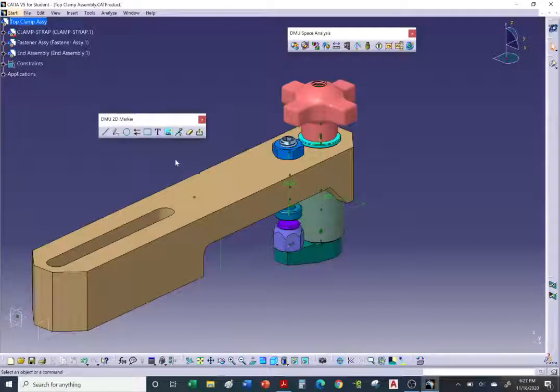Okay, so let's say, for example, I was checking your work, and let's say you used an iron knob here, this threaded knob, which serves as a nut, and you can just hand tighten. So typically you have knobs that work as nuts for speed. If you're going to be constantly clamping, unclamping, and not have to reach, so that you don't waste time reaching for a wrench, you can use a knob that'll serve as a nut.